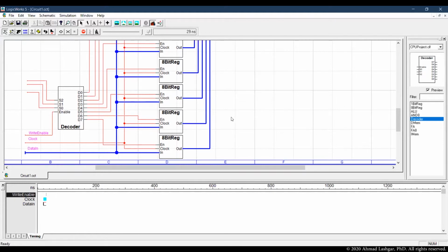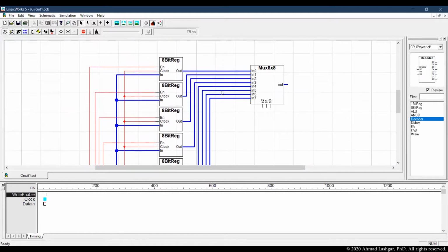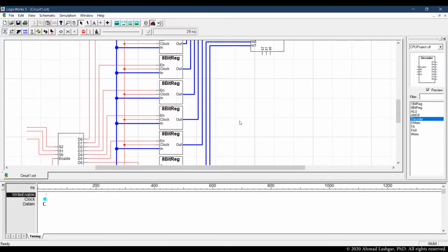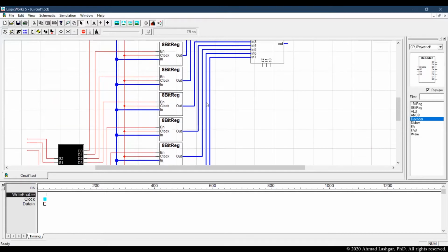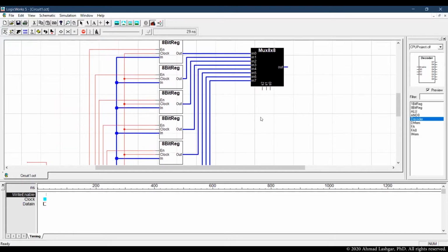So what I have here right now is the circuit complete for 1 write. So I can write 1 register and I can do 1 read. Let's verify the circuit is working with 1 read and 1 write. And if the circuit works as expected, we can extend that and add another multiplexer and complete the register file with 2 read ports and 1 write.